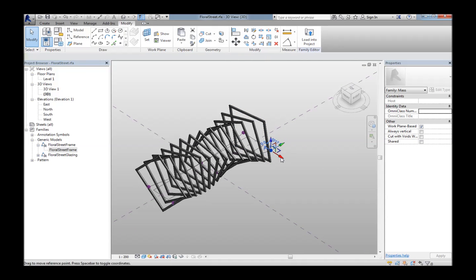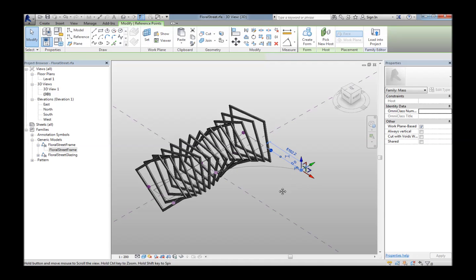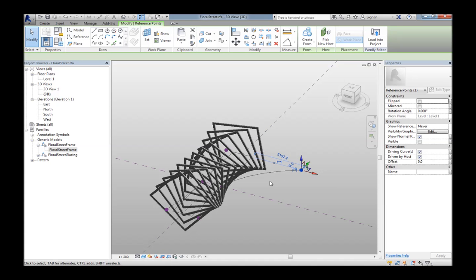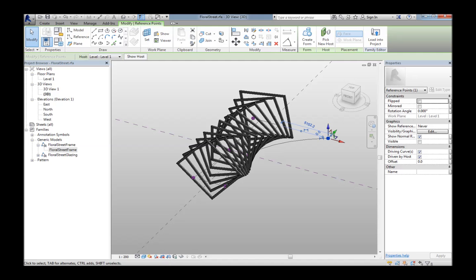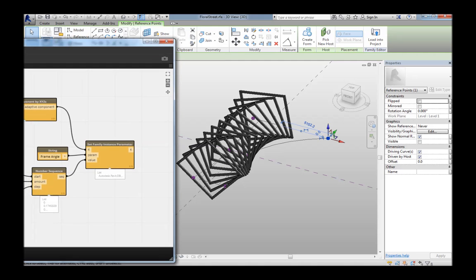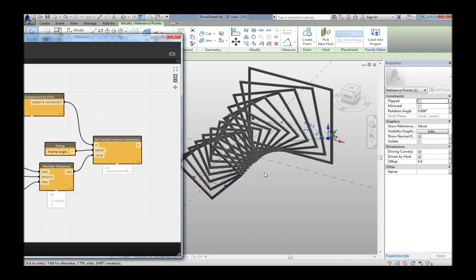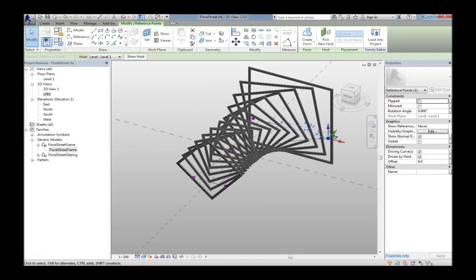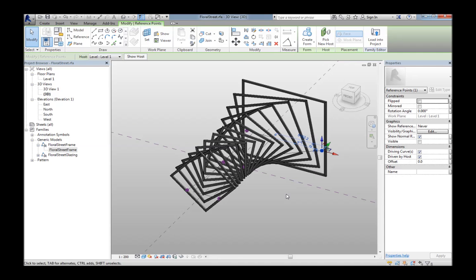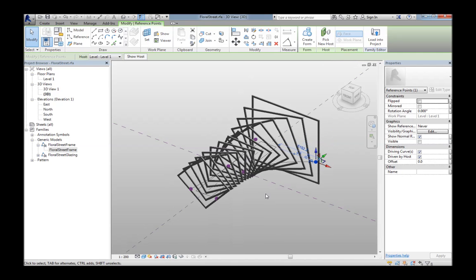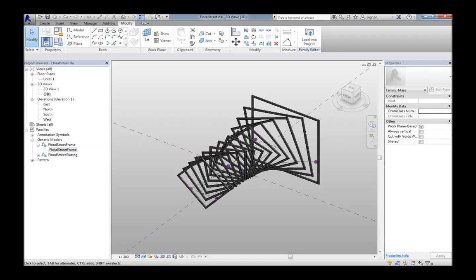And you can see we can change the rail spline. It doesn't track immediately, so you need to update Dynamo again because we're using that option of setting the adaptive point. The point is not being hosted on the line or spline. So if the spline changes, it doesn't automatically move with it, but it does update when you go back and hit run.